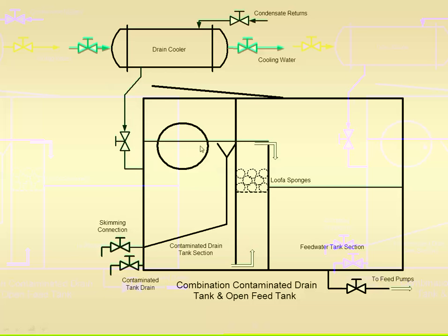That oil would tend to float to the top of this first segment of the tank. And then I have a diaphragm that basically extends down the tank and separates these two, except for a small gap at the bottom. So the water has to go down, around, and up, and the oil would stay on the top. That's the point. Make sure that you check this on a regular basis and that any oil is skimmed off.